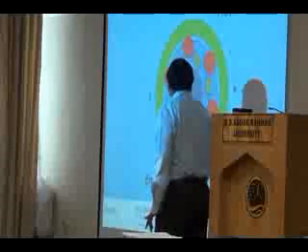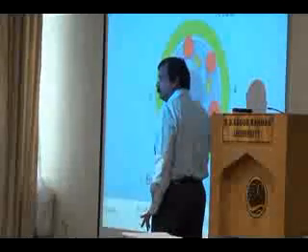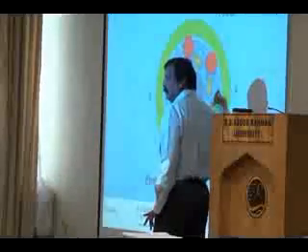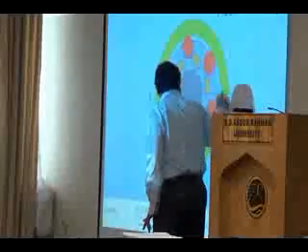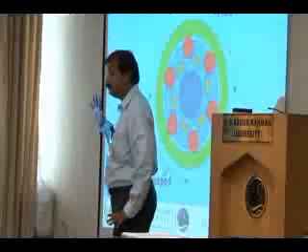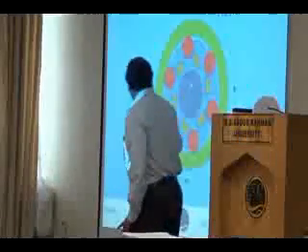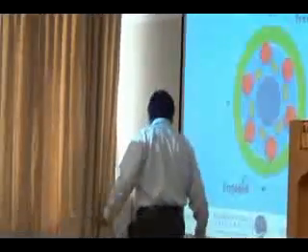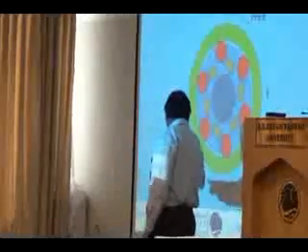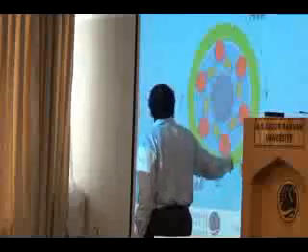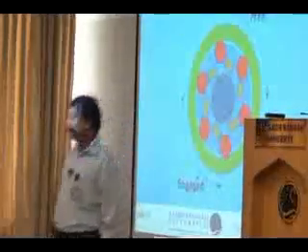Because it is pushed outward, this ball will come and then hit this surface, and then the green portion can rotate only if the inside thing also rotates. So when you rotate this way, the power will be transmitted. So I can roughly tell you, this is the pedaling direction. This is the idling direction. Okay.